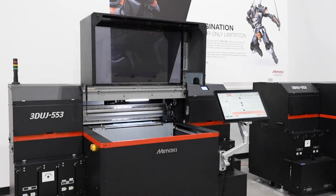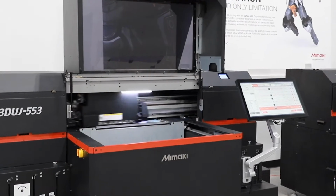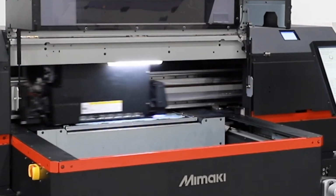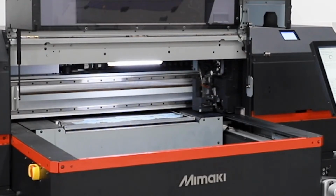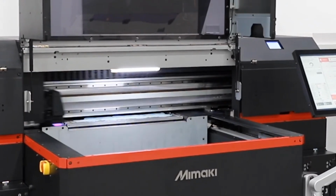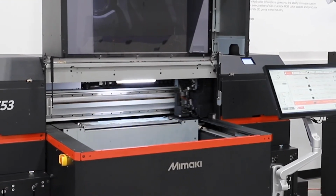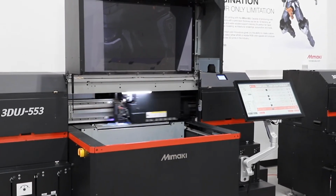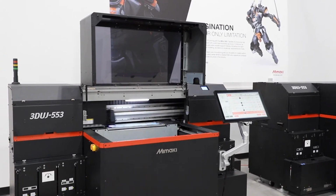This machine uses a dual LED UV curing system. On the carriage itself, there's 2 LED lamps. So as the ink droplets are being placed, they're being cured to a solid using these 2 lamps. The 3DUJ553 also uses a flattening roller to ensure layer thickness. We have 4 different print modes on this machine. High speed at 42 microns, standard at 32 microns, and high quality at 22 microns. We also have a special mode for clear that's 19 microns.